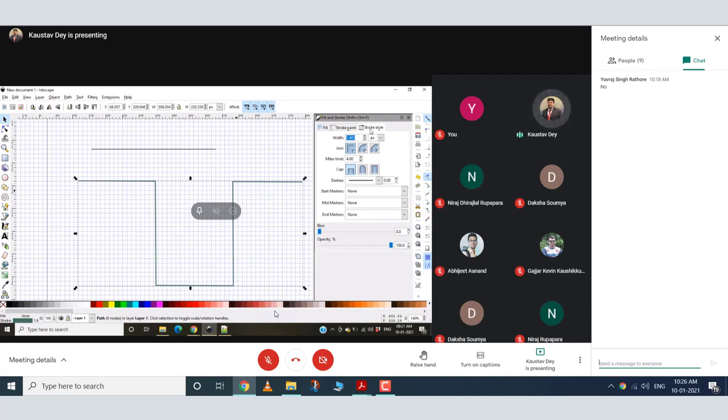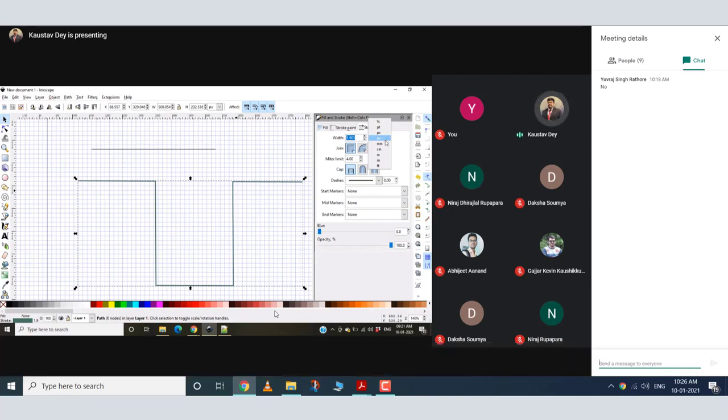Now stroke style has this where you can change the width. You can see that the width is set in a different kind of units. There is something called px, there is pt, pc, there are different units. So usually we try to define it in mm, centimeter, meter, but whatever unit it be, it has to look good. So I do it, say in px, and say I want to slightly increase this. So let me make it say 2.5.